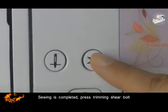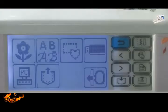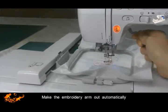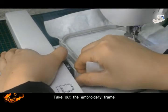Sewing is completed. Press the thread trimming button. After the completion of the dotted box, press the out key and lift the presser foot. This makes the embroidery arm come out automatically. Take out the embroidery frame.